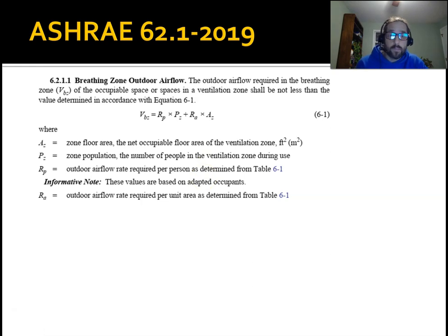You can vary the ventilation by using dampers and variable frequency drives and so forth. You can sort of throttle back fans and make them go faster and so forth, because you don't want to be providing ventilation all the time if you don't have to. So you want to provide the minimum amount necessary, because remember, with ventilation you're bringing in outside air. So if that outside air is cold, you have to heat it up. If that outside air is warm, you have to cool it down. And so there are a number of means by which you can modulate the ventilation to go up and down. But for now, what we're going to do is look at how much ventilation is required based on a certain capacity of people.